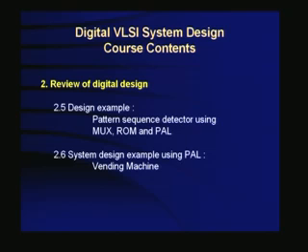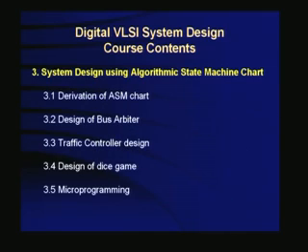And then from that you draw the ASM chart. From there you do the individual design of the controller and implement it using a ROM and a multiplexer or a PAL. All that will be done in this course. That is an introduction. So first you should know how to design an ASM chart.